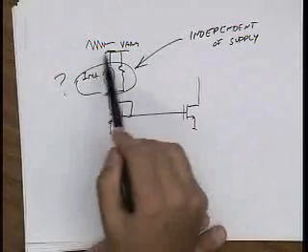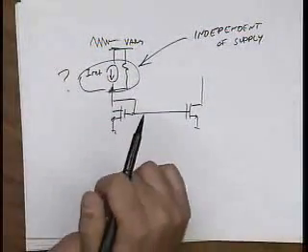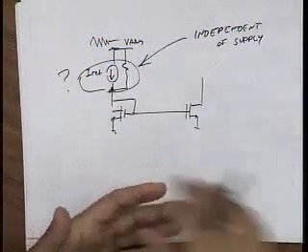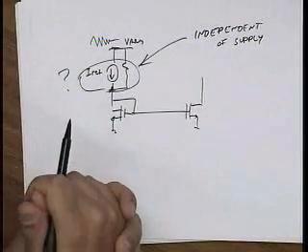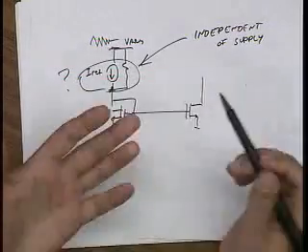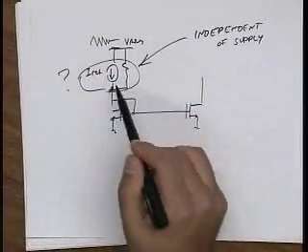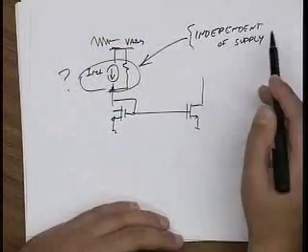Basically the supply is connected to all your circuit, including the digital, at some point. So there's going to be some natural ripple on that supply due to noise pickup. And if our bias circuits aren't insensitive to that, it's really a bad thing, right? So how are we going to design references that are independent of supply?